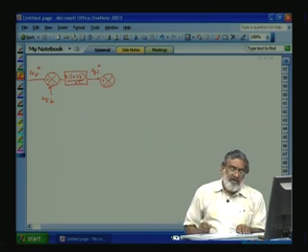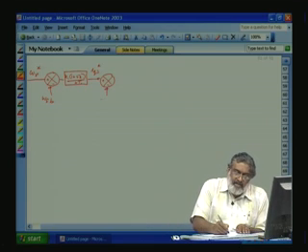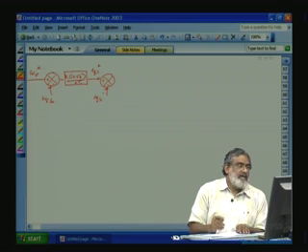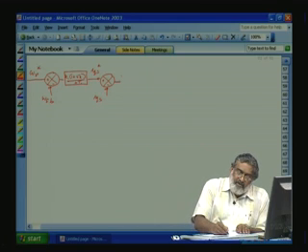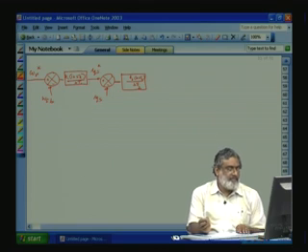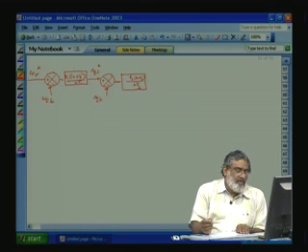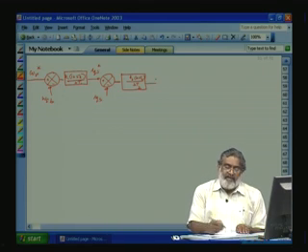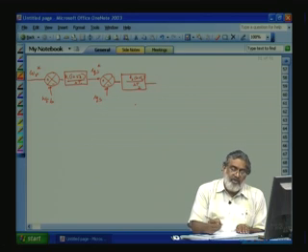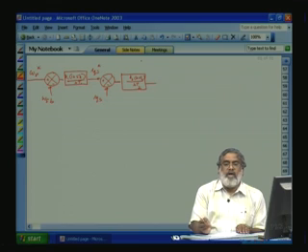the voltage control, we check IQS reference and IQS feedback. It's coming here. Okay. This will give it to the current controller, that is K2 into (1 plus ST2) by ST2. Okay. This controller output, if you use a current hysteresis controller, this output IQS and IDS we can directly convert into IAS reference, IBS reference, ICS reference.